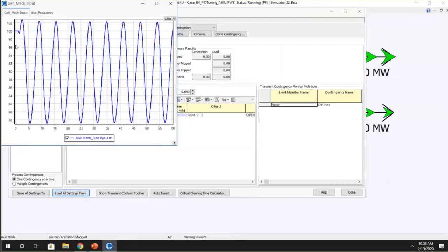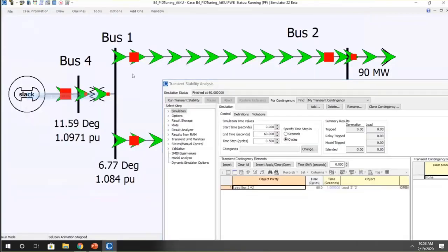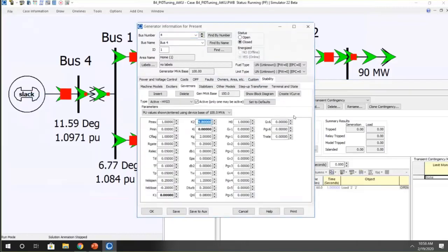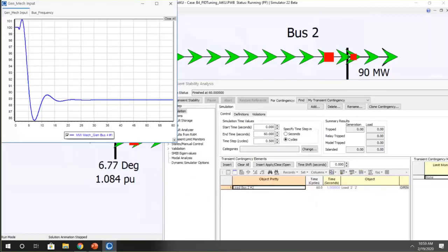If I wanted to tune this with just proportional gain, what the approach says is set the K value to 1/2 of this value. So we would know the K value where it just starts to oscillate, and you could get that by trial and error, and you'd also measure this period of oscillation, and that would be your Tu value. So if we go in and change the value here on just the proportional gain from 9.8 to 1/2 that, which would be 4.9, save it, click OK, and run it, now we get a pretty good response. You look at that and it kind of works like magic.